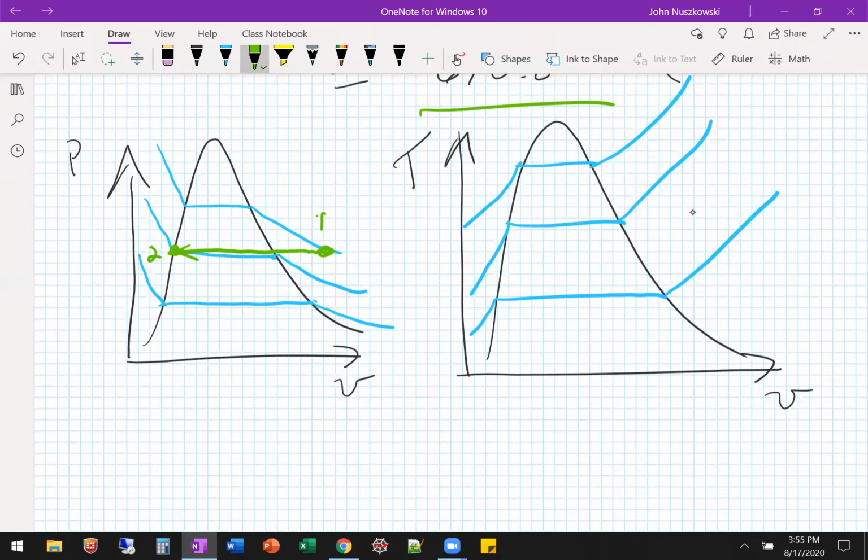Now we had our constant volume process. So that means we have a vertical line. So we can either go up or down then. If it's constant volume, we can either go up or down, right? And we're a saturated mixture, so that means we have to go down, okay? We're not compressed, so we're going down, right? So let's see how awful my vertical line will be. Too bad. All right, so then we have our state 3, okay?